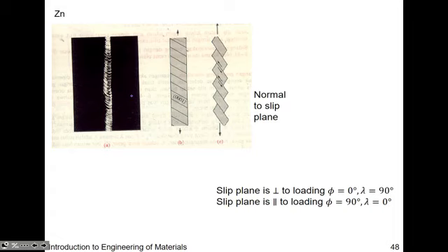And so an example here is zinc, HCP. And you could see the basal plane. We didn't go into depth about basal planes of HCP because we only focus on FCC, but the gist of it is that in the plane, and you're not going out of plane, in the plane, the atoms are close packed for hexagonal HCP systems.